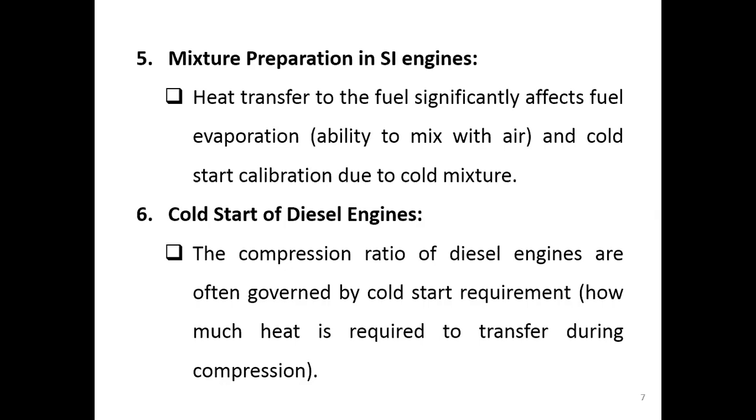You do the compression, and you expect that the heat that comes out because of compression should go into the cylinder to help ignite the fuel, and then combustion happens. But instead, some of the heat goes out to the surroundings because the surrounding temperature is lower. So this is how heat transfer has an impact on the cold start of the diesel engine.